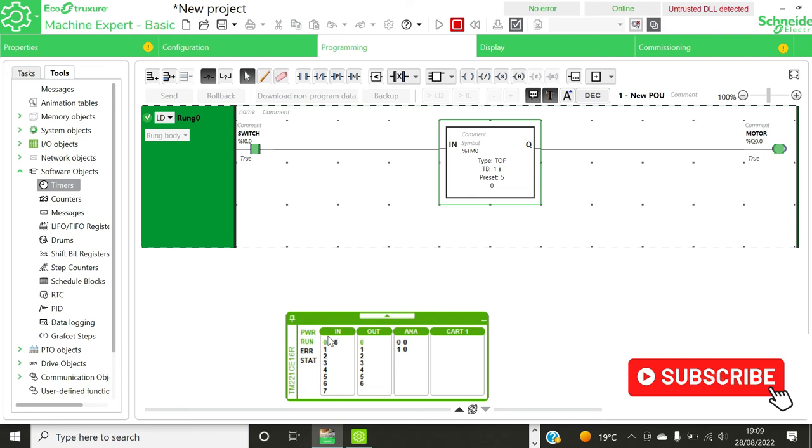You see, when we switch off, the motor is still running and the timer is counting. After 5 seconds, the motor goes off. We then have a pulse timer. A pulse timer, it gives an output for a specified duration of time. For instance, if we change this timer to be a pulse timer, TP, then we set it at 10 seconds. We say apply.